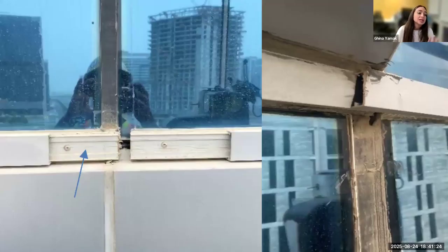Those images are just examples of bad installation of the facade. So the facade is there. Maybe the facade was designed really well, but the contractor just wanted to not add this layer of pressure cap to the curtain wall, and this will lead eventually to bad performance. It will lead to leaks. The curtain wall will not perform the same, of course.